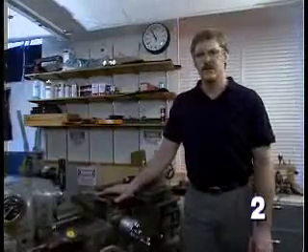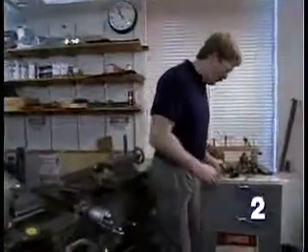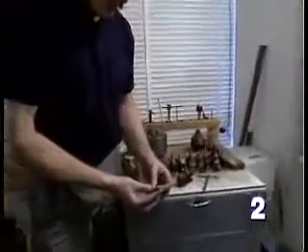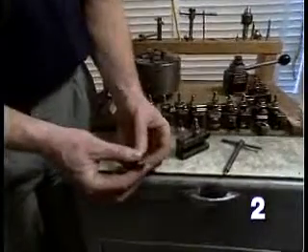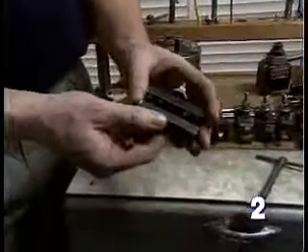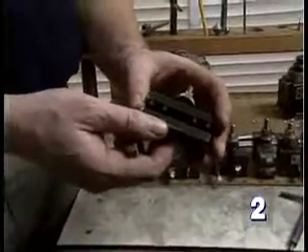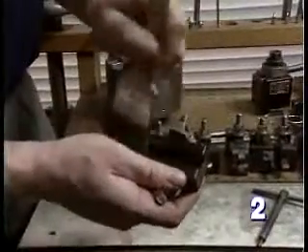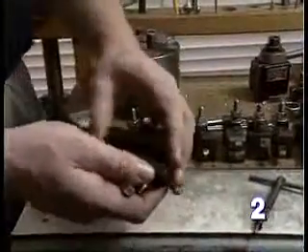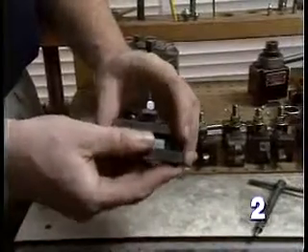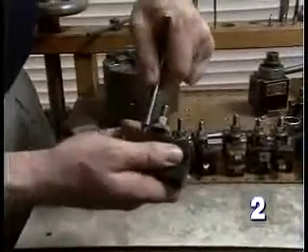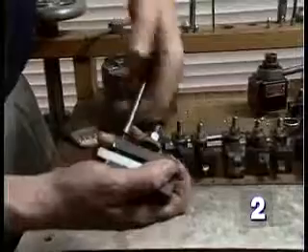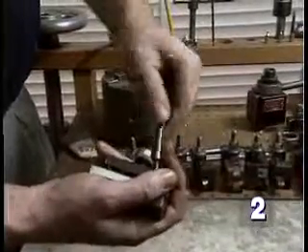Many different types of tools are commonly used on the lathe. This is a standard lathe tool. These tools are commonly held in lathe tool holders. Install the tool, making sure the tool holder is clean. Tool in place, and lock the tool down securely.